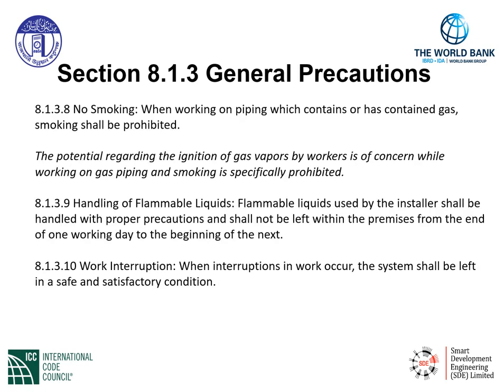Given the precautions that we've gone over, there are a few more safety concerns indicated in this code, specifically smoking. Section 8.1.3.8 gives us this requirement: when working on piping which contains or has contained gas, smoking shall be prohibited. This is a major concern here.